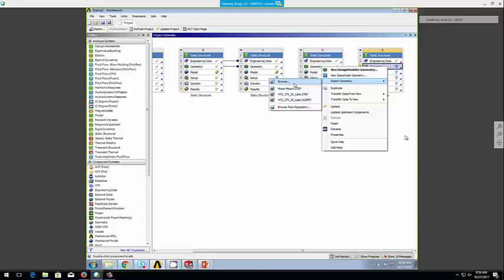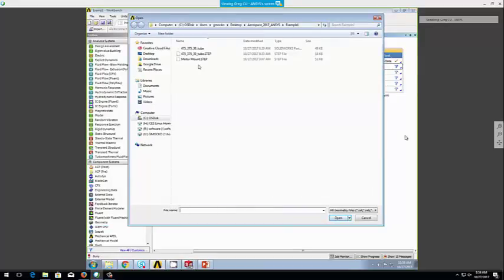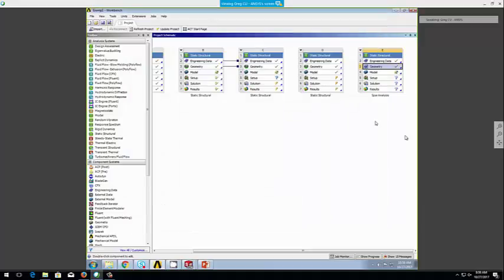So let's see. I may put on, say, a Y component of, I don't know, 0.25 of a pound. This may be the mass of your motor. I might then put an X component on here that is going to be, say, a thrust. So I'll throw 15 pounds at it. In this case, it's pulling out. So maybe it's best that I make it negative 15 pounds. So now it's going to go the other way. All right, so now I have specified the weight of the motor and then the thrust of that motor.